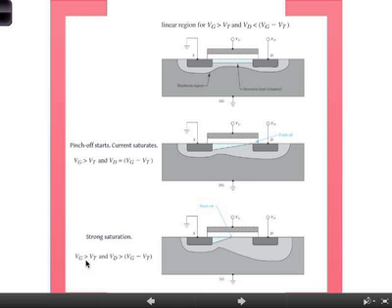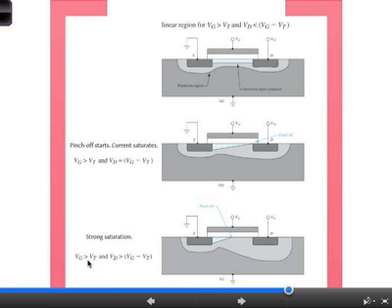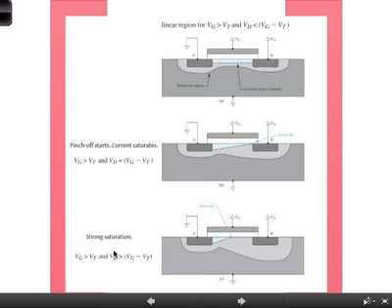And typically the threshold voltage is shown as VT, and that's a saturation condition. We know that the drain voltage greater than VG minus VT means that condition right there, where the depletion region pinches off the inversion region. Okay, so those are two things to keep in mind.